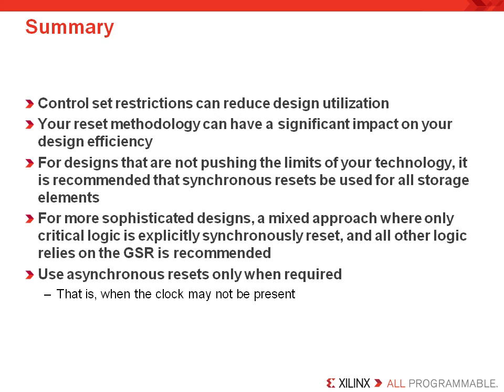For designs that are not pushing the limits of your technology, it is recommended that synchronous resets be used for all storage elements. But in most cases, we virtually recommend synchronous elements all the time. For more sophisticated designs, a mixed approach where only critical logic is explicitly synchronously reset and all other logic relies on the GSR is recommended. So in that case, you use the GSR to reset your entire design, and then you use local resets throughout your design when necessary. Just make sure they're synchronous. Also, asynchronous resets should be used only when absolutely required. That is, when the clock may not be present.